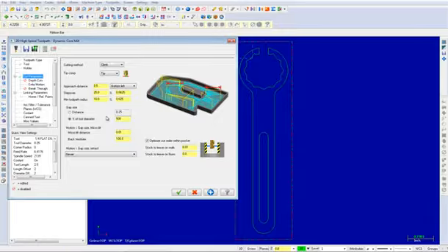Motion, Gap Size, Retract controls retracts in the toolpath when making a non-cutting move within an area where the tool can be kept down or micro-lifted. And finally, Optimize Cut Order defines the cut order Mastercam applies to different cutting passes in the Dynamic Mill toolpath. Once the parameters have been adjusted as shown, select the entry motion.